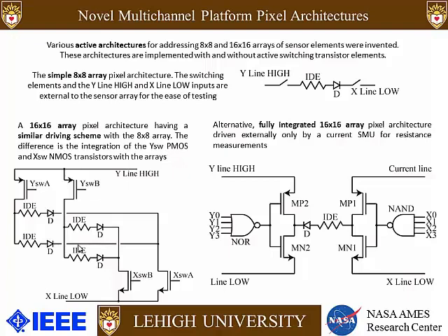And then at the end, I'm going to present a fully integrated 16x16 array pixel architecture where these logic gates are internal to the circuit, as well as those inverters, as well as the Y line high, X line low, and current line. And the only thing that is connected external to the entire setup is a SMU, which stands for source measure unit, where one can force a current and measure the actual voltage while the current is forced into a specific node. And we use those SMUs only to acquire the data.